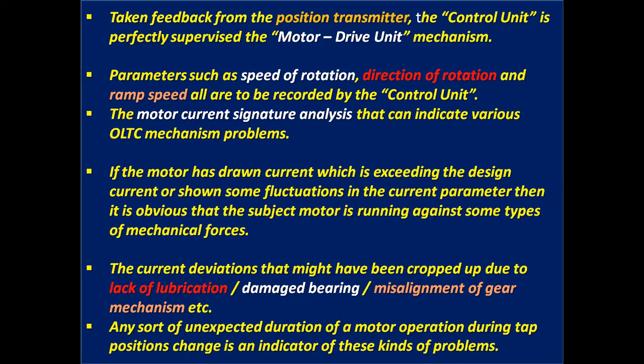and it is effective from a maintenance point of view. If the motor has drawn current exceeding the design current or shown some fluctuations in the current parameter, then it is obvious that the motor is running against some type of mechanical force.